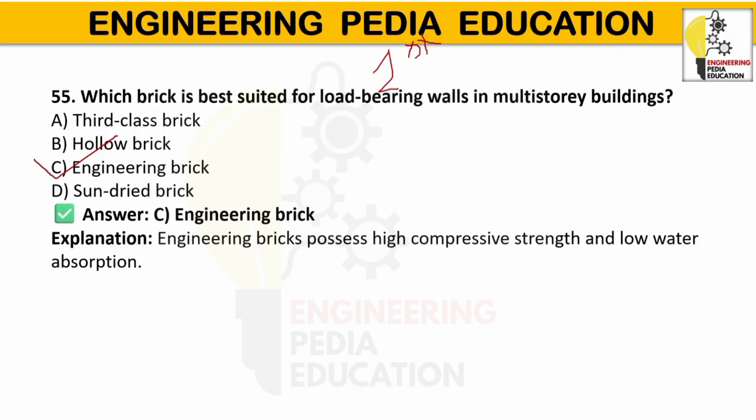What are engineering bricks? Engineering brick can be defined as specially manufactured brick having high compressive strength, low water absorption, and high durability. Very high strength, low porosity. Water absorption in this type of brick is less than 7%. Resistance to dampness, chemicals and frost. Uses are foundation, retaining walls, sewer manholes, DPC, and heavy engineering work.